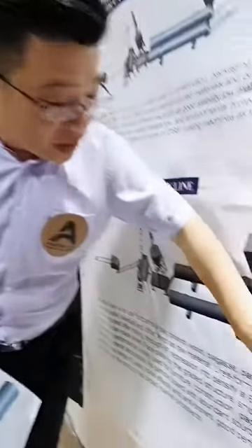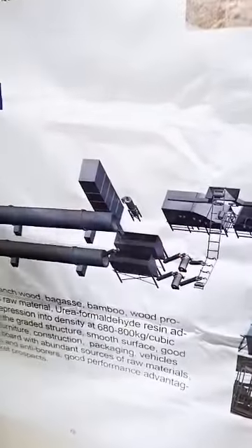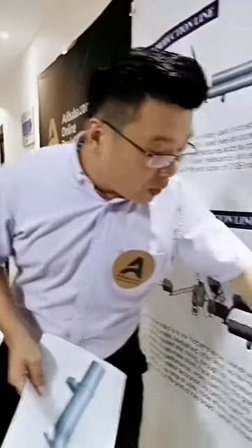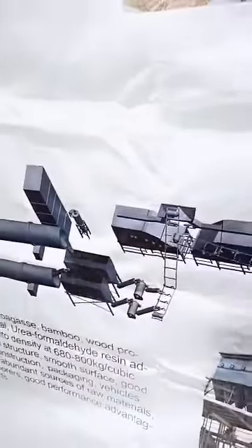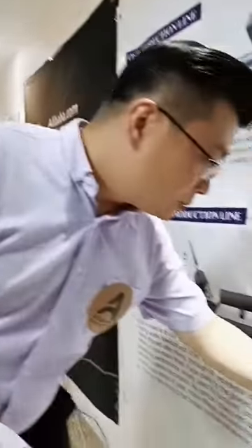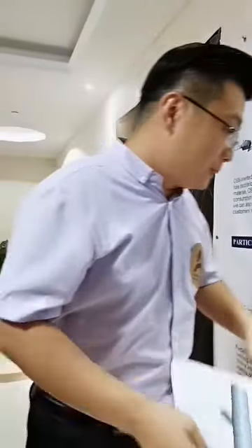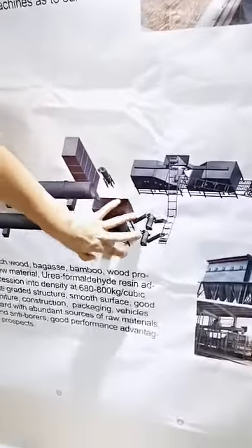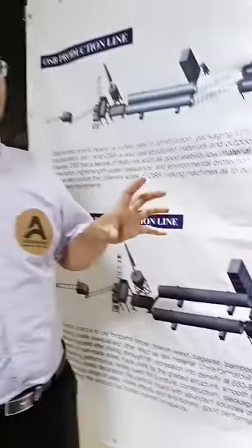Here, not all the oil is blended. It's like rain, sprayed on top of the glue with the prefix, like a shower. When you take a shower, the water comes out like this, and here the oil comes. And in the middle, you can see there's some space to rotate and mix. It's a full, complete mix of the glue and the prefix and the rest. And for the glue, the solid content must be at least 60%. It's better to have more than 70% solid content.